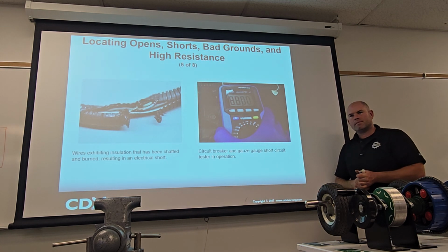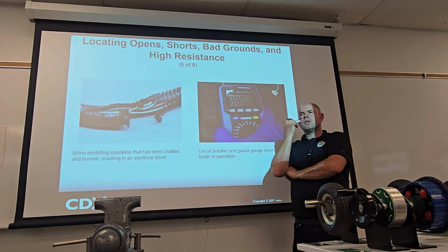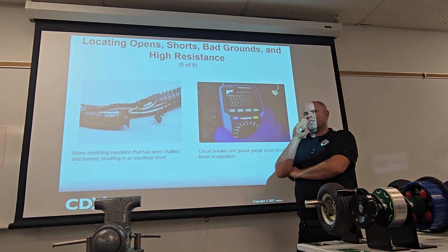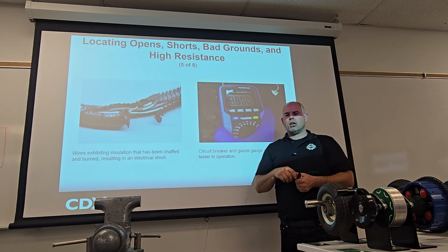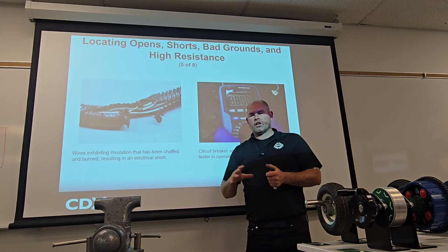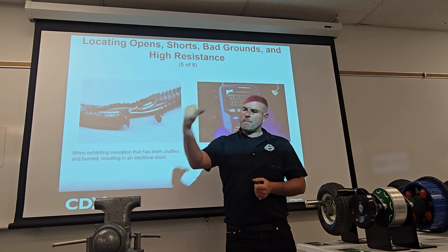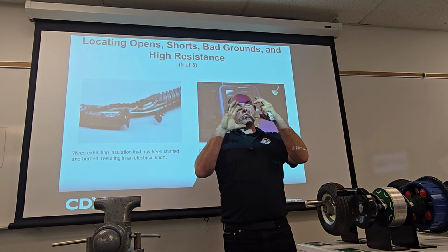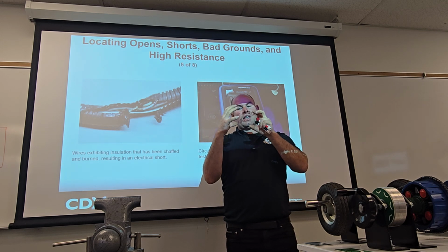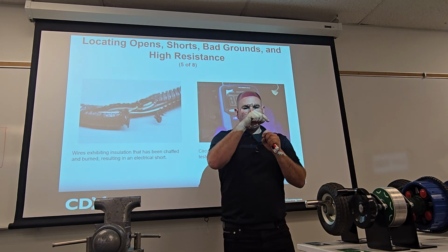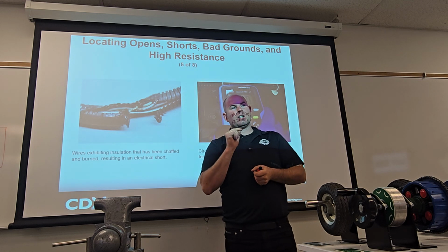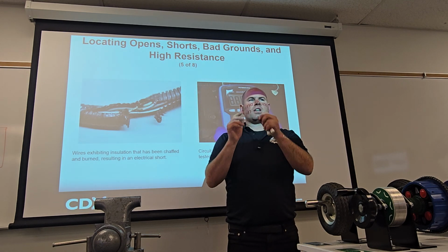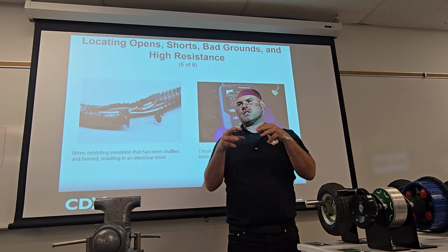Go ahead. So a short to power would be like, for example, the fuses that go to sound systems, the ones that are directly on the battery. Would that be considered a short to power? So let's say you guys have seen those where it's an aftermarket audio system and somebody's got to put a big wire on the positive terminal, and then you bring it over here to the fuse. Those fuses usually come with a big plastic case. The reason they do that is because any bare metal in that big fuse would be a potential short. So usually they have you put it in something plastic so nothing can fall in there and accidentally touch a positive, right?